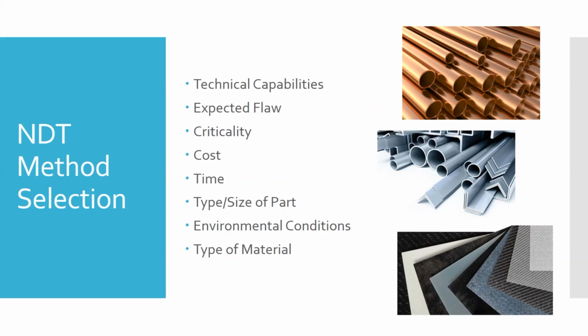You can do the same thing when we do eddy current. You've got a little pencil probe, and you can check for cracks around every rivet by doing that. Or you can get a big sheet array, a whole bunch of probes all together, where you can run that over and do a big area much quicker. But that array probe and the tester that goes with it costs a lot more than the pencil probe and the single channel tester you would use. So you have to decide what's best.